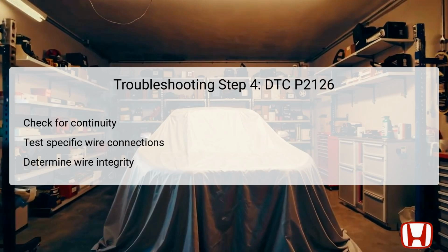The fourth step involves checking the continuity of the VCC5 line to confirm its integrity. With the vehicle still in the off-lock mode and both the APP sensor 6P connector and PCM connector A50P disconnected, the technician should measure continuity between the same test points identified earlier.